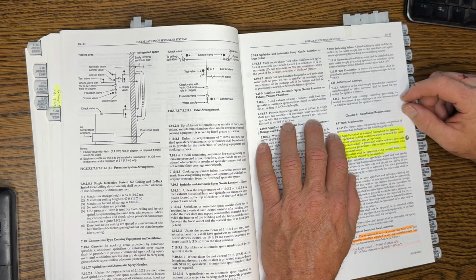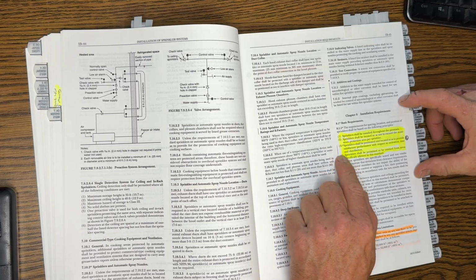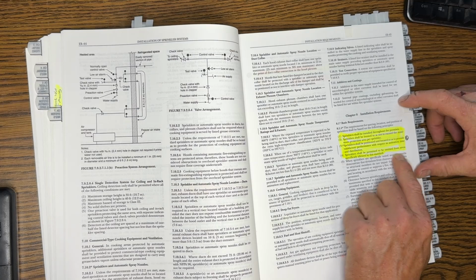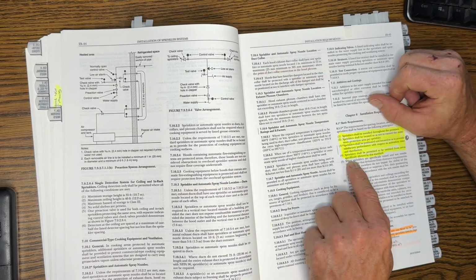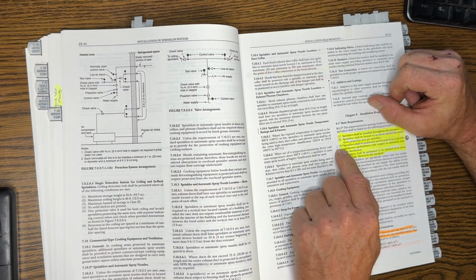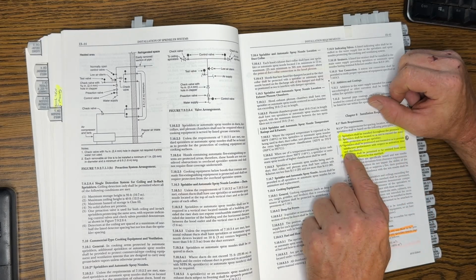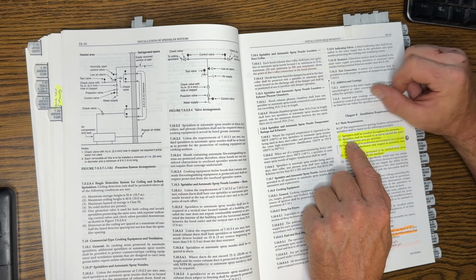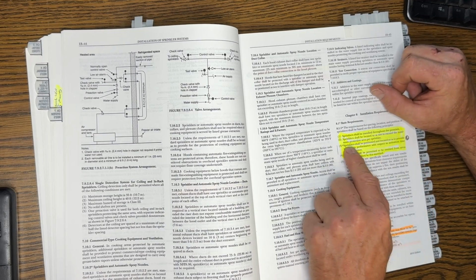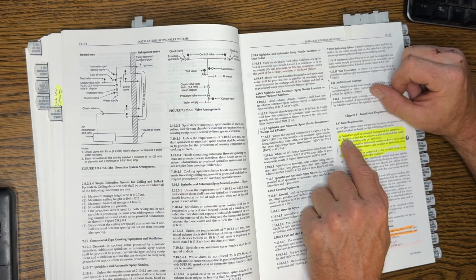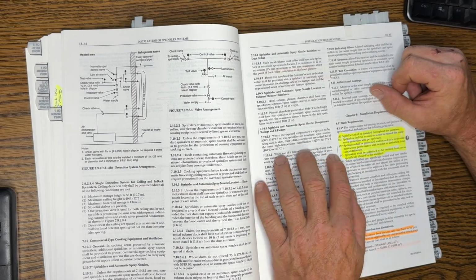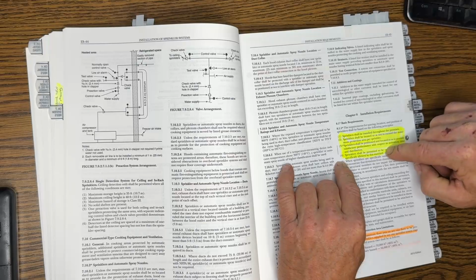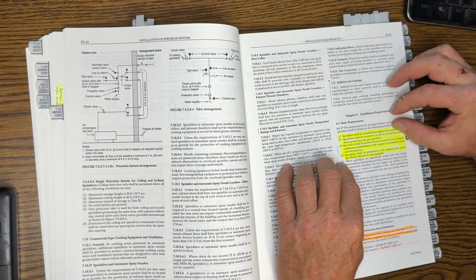Sprinkler heads can be omitted from undesirable locations. So which section was that? Throughout the premises, sprinklers shall be, there. Sprinklers shall be permitted to be omitted from areas specifically allowed by the standard. Sprinklers shall be positioned and located so as to provide satisfactory performance with respect to activation time and distribution. Sprinklers shall be located so as not to exceed the maximum protection area per sprinkler. Sprinklers shall be installed throughout the premises. So if you read that and then you read item 4 specifically, you could easily get duped,